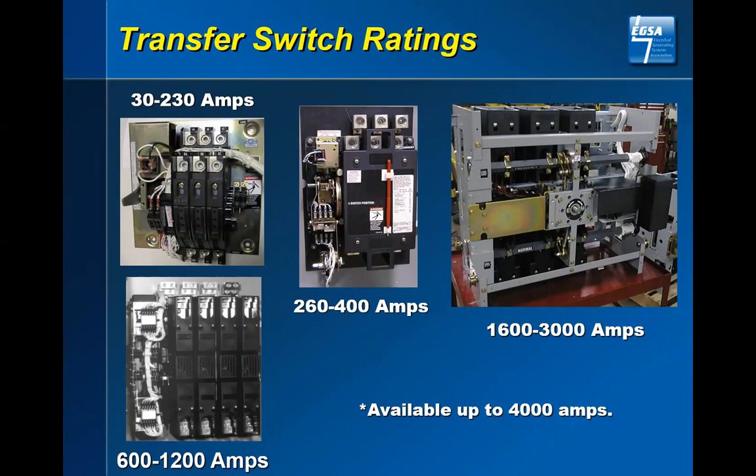The point to this is two things. Number one, when you're looking at the correct switch to put into your application, it is not only the ampacity, it is what that fault current could possibly be.